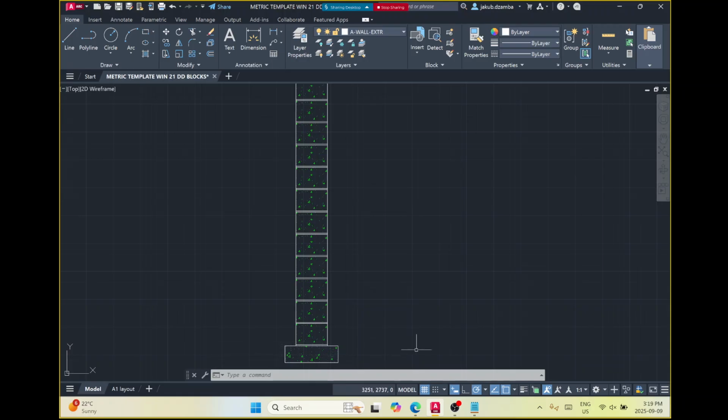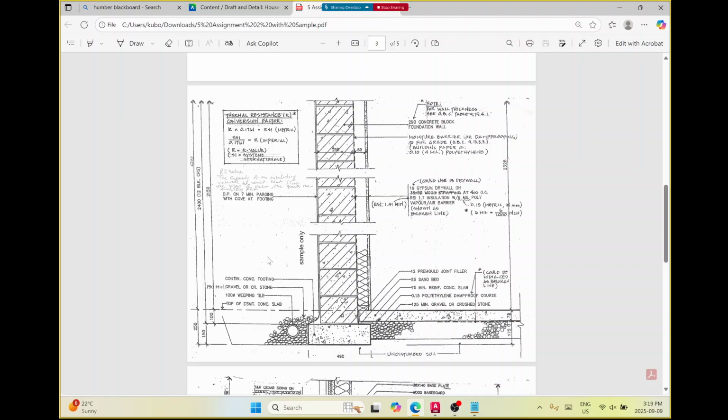Now you may notice that our drawing, the one we're going from, doesn't show 12 blocks. It shows 1, 2, 3, 4 ones, kind of a slice, another slice, and then a couple more. And so this is a convention that you can use when drawing. When you have, let's say, a lot of blocks or something vertical that is the same condition happening and just stretching out and taking up space, you can throw in these squiggly lines. They're called breaks. And you basically delete what's between it. And it's assumed that whatever is between it just keeps happening. You know what I mean?